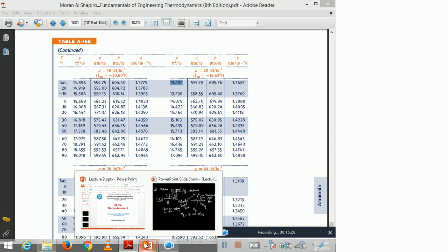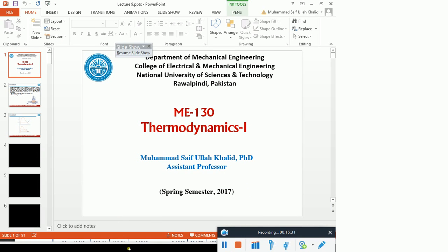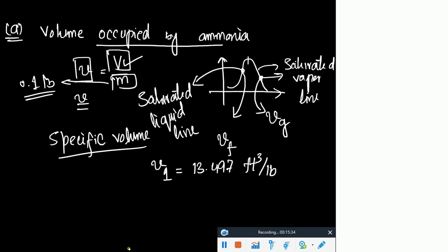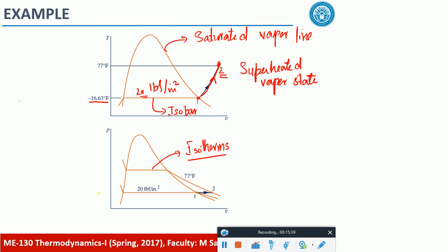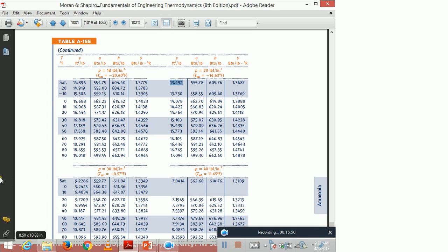the point is, let's go back to, I'm sorry, yeah, let's go back to this thing. Just look at the second state. On the second state, your temperature has increased, isn't it? Pressure remains the same, but temperature has increased. Now, just look at that table and tell me, can you guess now where is the temperature? You only know the first saturated temperature because it was lying at the saturated vapor line. Now, can you tell me how would we determine the second temperature?